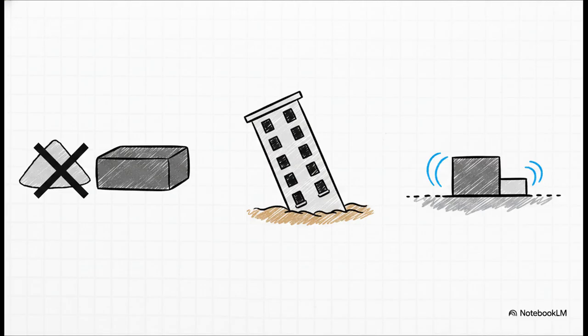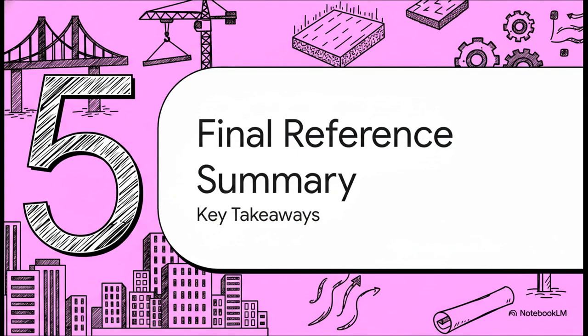And third, a lot of students misunderstand the plinth versus the foundation. Look, the foundation is the substructure buried completely below ground. The plinth is the base structure sitting just above the ground level, explicitly designed to protect the interior from dampness and surface water. Let's wrap things up with Section 5, Final Reference Summary.